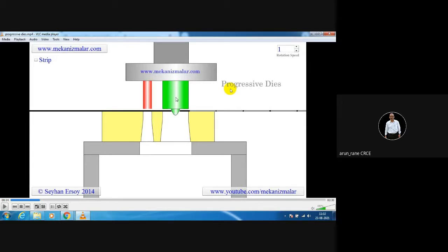Now what happens when you are doing blanking, the inside hole and the outside diameter should be concentric to each other. So when you are doing the blanking operation, you have to take a reference of the hole. So this is a conical shape which locates the hole in the strip, and then the blanking happens, so that the outside diameter will be concentric with the inside diameter. And why is this tapered? So that it enters progressively and easily in the strip. So that's why it has a slightly tapered shape.